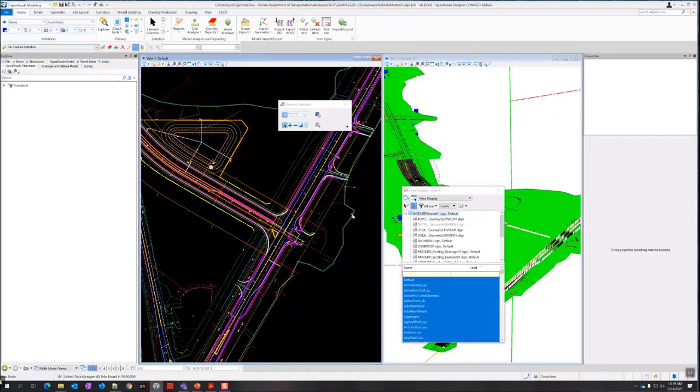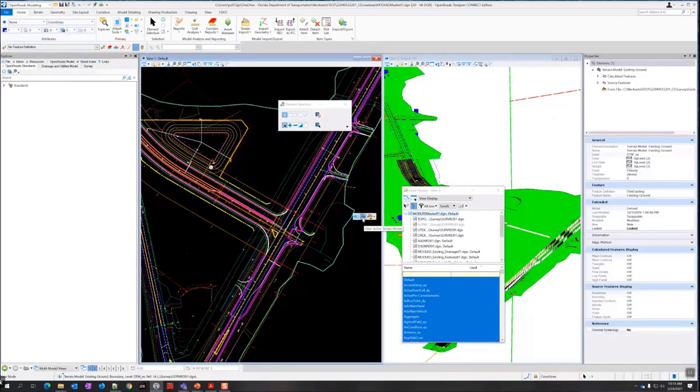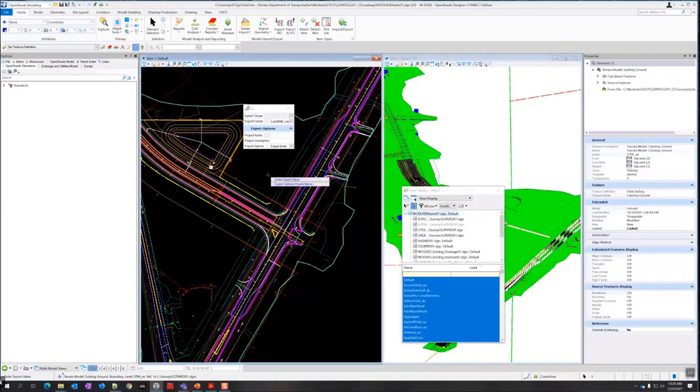If you hover over this surface and get the little pop-up menu, same as where we went to set it as an active terrain model, this third button here has a drop-down. Click that drop-down, and right in the middle, we have LandXML. So I'm going to pick LandXML. A few options come up here. For project name, we're going to call it AMG 3 Surface EX01. This would be the standard naming convention for that.